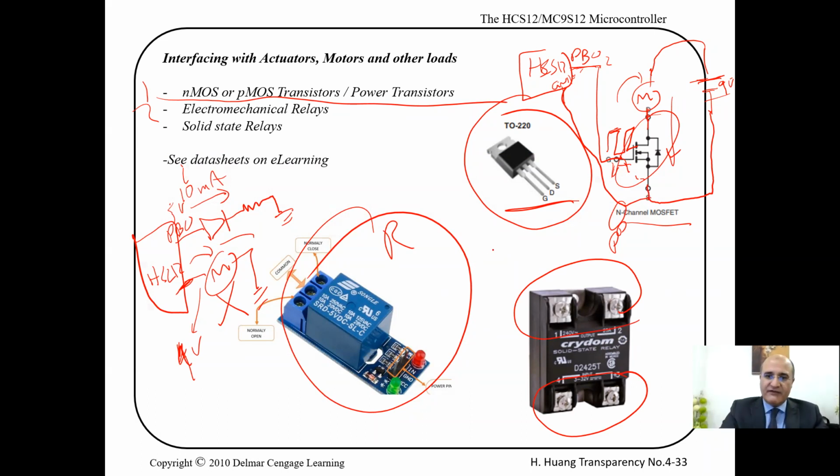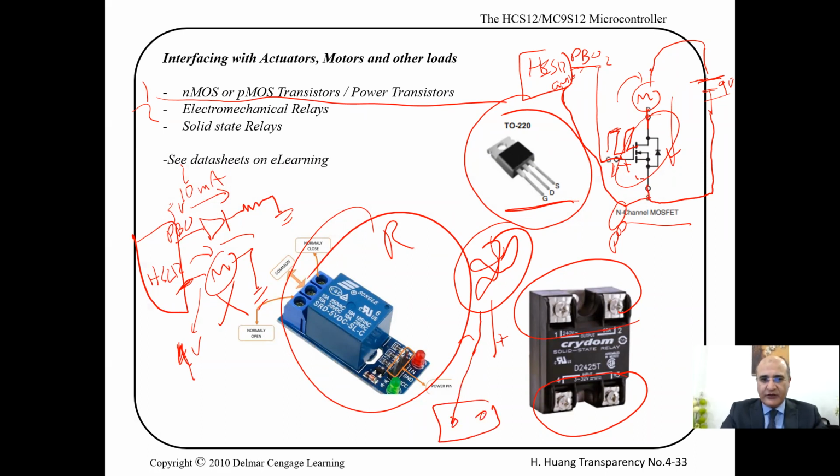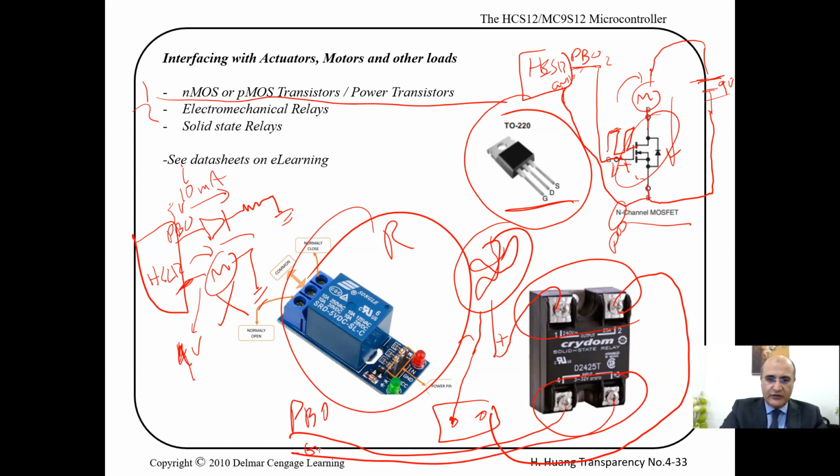So you have a fan, an AC fan, مروحة. Okay, المروحة, it has a plug, right? The positive and negative that you take from your power outlet. So how to connect it? This is the power outlet. Take the negative part, connect it. The positive part, connect it here, and take a wire then to the positive. And here, you take this to port B0, for example, and this to the ground of the microcontroller.